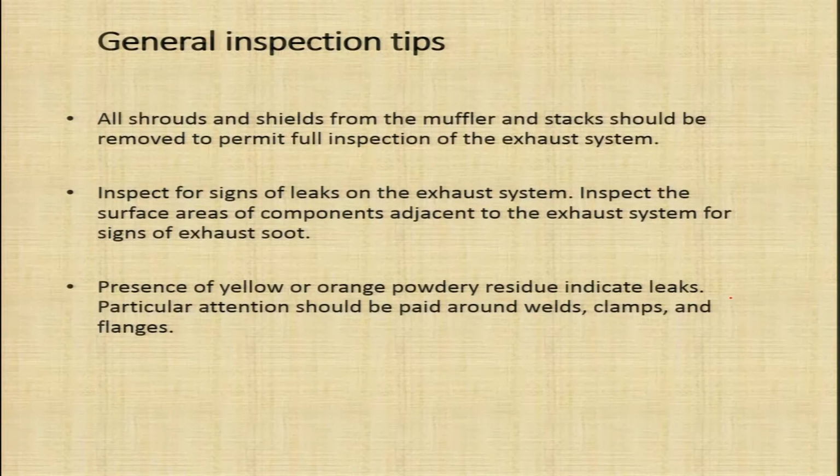Now, let us see the general inspection of the exhaust system. All shrouds and shields from the muffler and stacks should be removed to permit full inspection of the exhaust system. In order to carry out a detailed inspection, the shrouds and shields should be opened. Inspect for signs of leaks on the exhaust system.